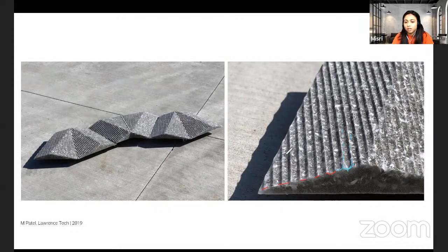The difference between these toolpaths at that point was about 10 millimeters, so it was contoured at a distance of 10 millimeters. But if it was really fine, so close that it goes down to something like 2, it would essentially mean I would have a smooth geometry without any ridges. That's something I'll leave up to you when we start diving into the tutorial.